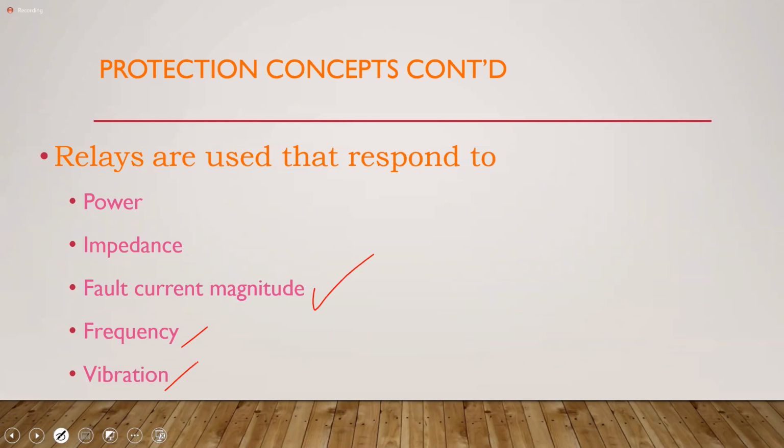Now, I hope by now you'd appreciate that how I protect a transformer would therefore be quite different from how I protect a generator. We spoke earlier about the earthing impedance. The generator, I don't want to have it solidly earthed, because if I have an earth fault, the current that is going to pass through that generator may render the generator useless after.